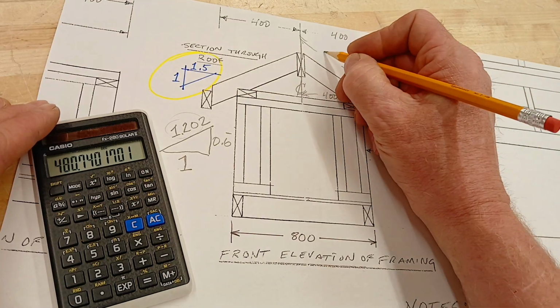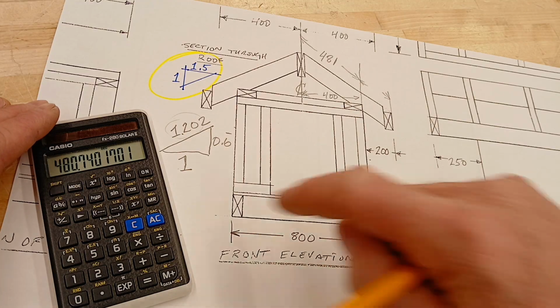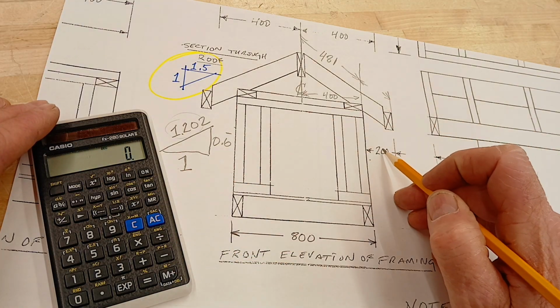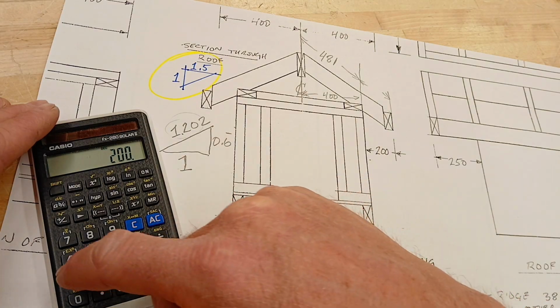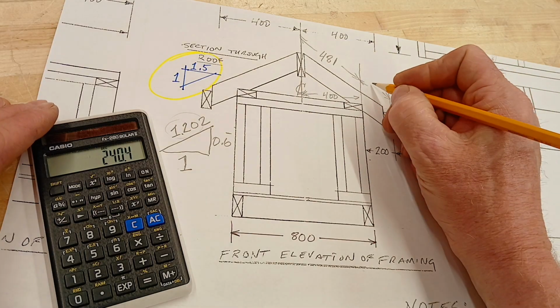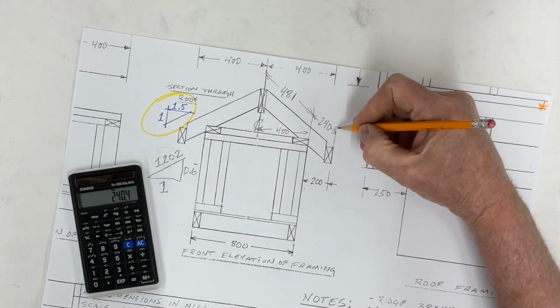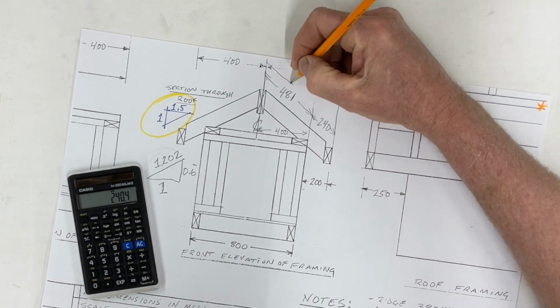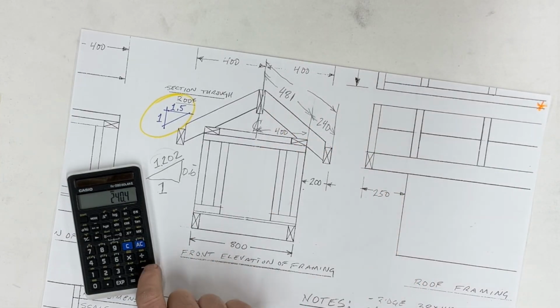When calculating the tangent and the secant, avoid rounding your numbers to ensure that your final result is accurate. But once you have your final measurement, round that to the nearest millimeter, because that's as close as you can actually measure on your tape. While we're doing calculations, we'll get the total of these two line lengths onto the drawing as well, so that we can avoid compound error by measuring both points from the same reference point.